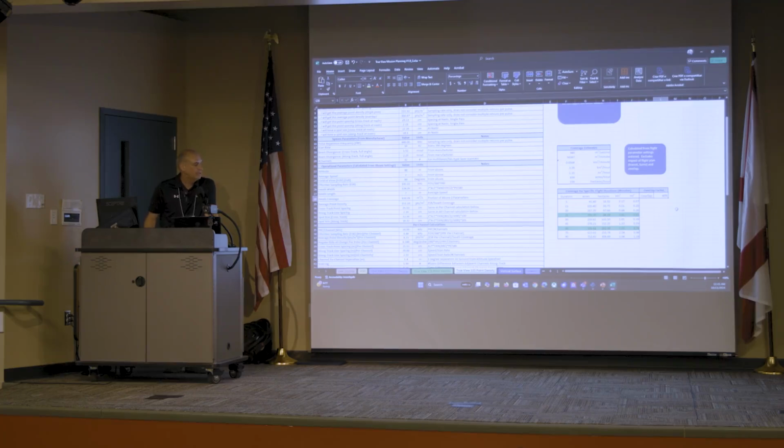Just to show you an idea, if I have, let's say, just one camera, and I want to do the same flight to get the orthophoto as well, I will probably need to change the overlap to, let's say, 80. So you can see that the productivity is much smaller right now, because I'm leaving the flight lines much closer. So you have less productivity. That's the reason you're using a system with, in this case, 3 cameras or 2 cameras. You're going to have much more productivity, right?